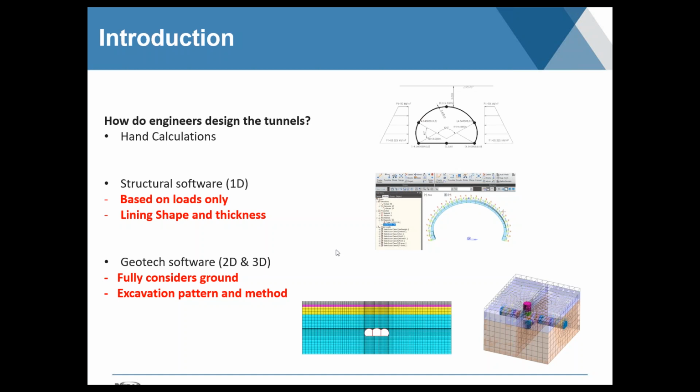Whereas the next level beyond that is actually considering the ground elements, either in 2D or in 3D, and that's really when you can get beyond just what the support system should look like, to what the pattern of excavation will be, especially once you hit 3D, as well as considering the nonlinear behavior of the local ground conditions that just cannot be done with springs.